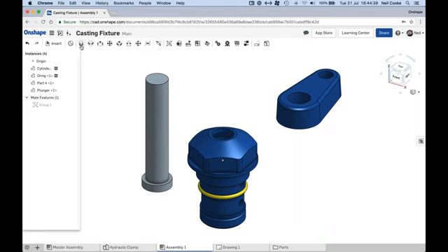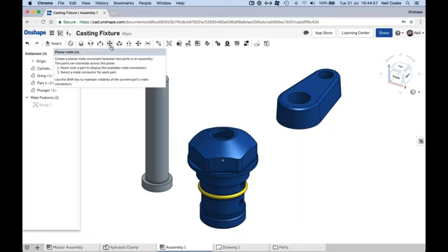But in general, the first 3 and cylindrical are probably the ones you're going to use the most. It's quite easy to spot a new SolidWorks user coming from SolidWorks to Onshape, because the mate list is full of planar mates, because people are trying to add lots of planar mates to constrain something together, but there's no need to do that.